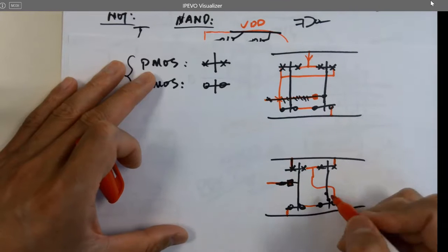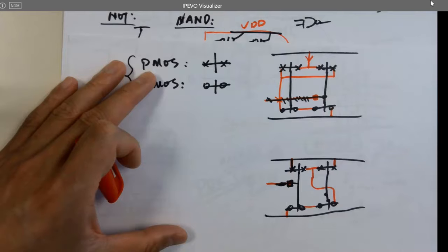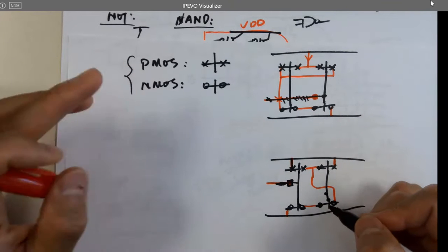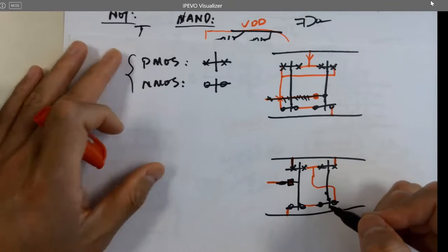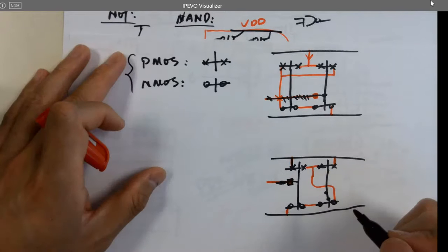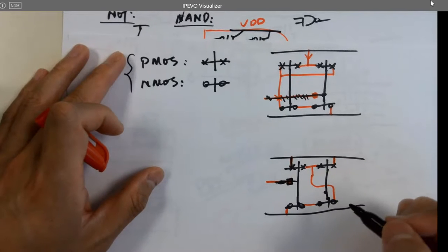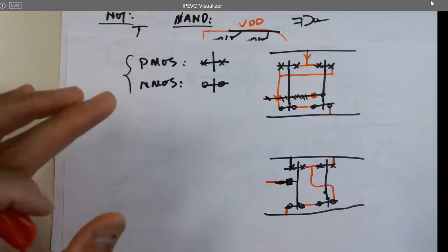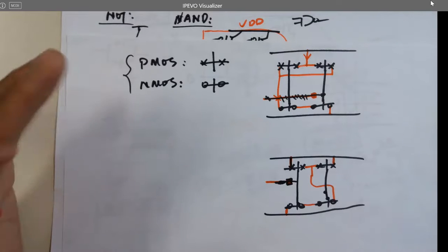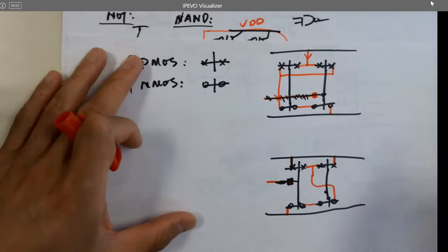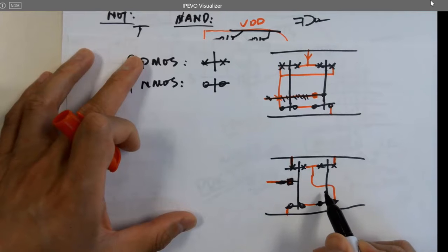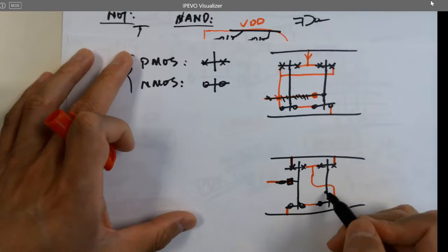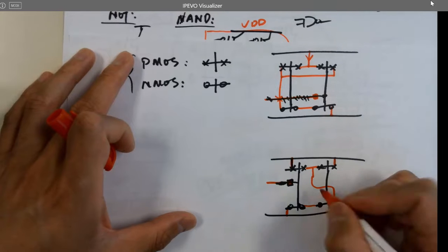What about this one? As long as you're comfortable with the length, just look at it. As long as you can use more metal, just use more metal. There are always trade-offs in between, the layout, efficiency, and also the lengths of metal and poly. So, for example, here, I don't have to use any long poly. So right after it, I just introduce a via to metal 1.